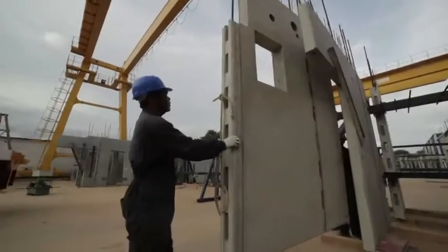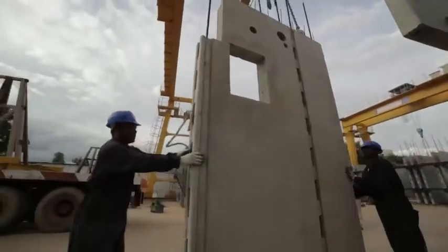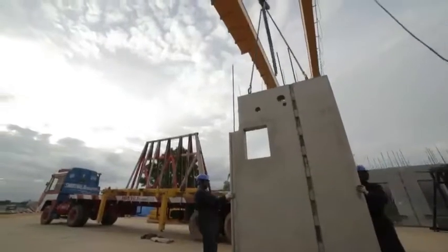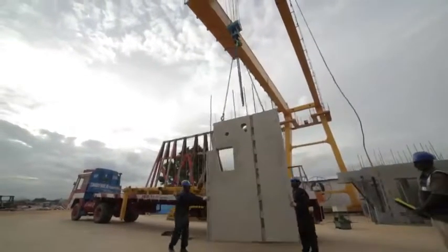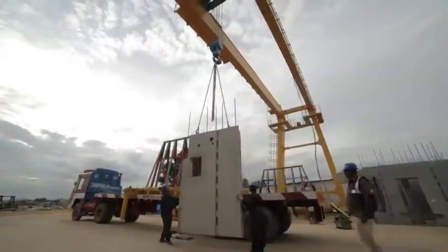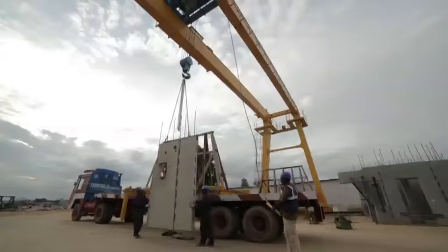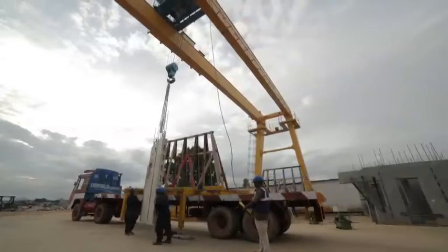Transportation. Concrete cubes are tested at the laboratory, and only after achieving the desired strength, panels can be transported. The approved precast elements are transported to the respective position on the site for erection. Wall panels are to be transported on A-frame trailer and slab and beams on flatbed.